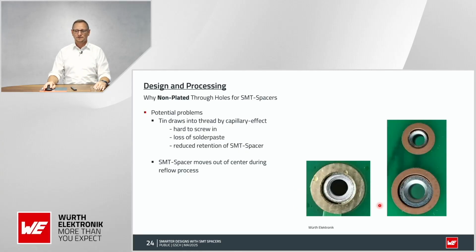Depends on the direction. If you have the heat on the one side, then of course it gets liquid here. And the component is always drawn to the side where the solder gets liquid. And in that case, here a gap could appear. And with a gap, the problem is that solder could drop down.